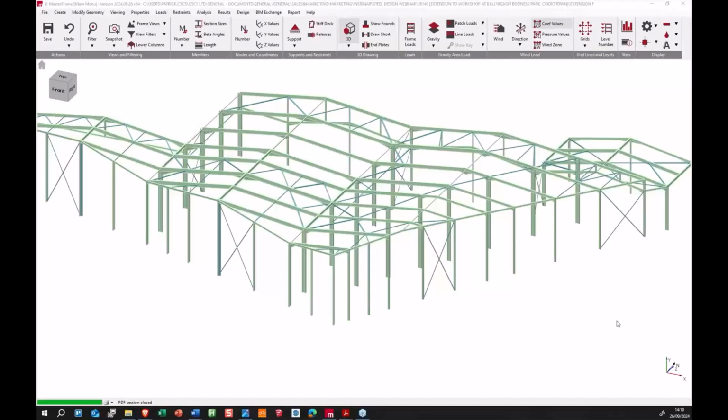Less so applicable to the Eurocode because its method of calculating the elastic critical load factors is more built into the ultimate loading combinations through the ratios of the vertical and horizontal load with the deflections associated with each of the ultimate cases. So it wouldn't be so appropriate to use the 10% there because you are working with your ultimate load combinations in the calculation of that.